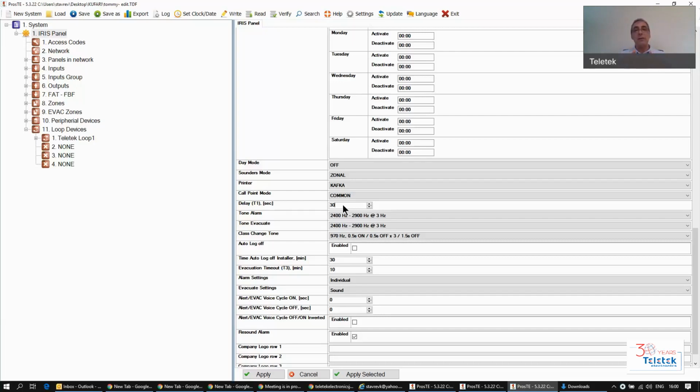So if that time expires without any action on the silence buzzer on the panel, the panel will start the silence right away as soon as this delay expires. If within this delay, T1, somebody presses silence buzzer, the panel considers that the fire event is acknowledged, and somebody is going to go and check the zone with fire, whether it's a real one or a false alarm. So we'll jump directly to the T2 delay that you set up for the zones.